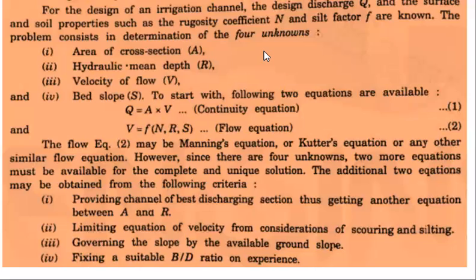And also the hydraulic mean depth R. So what is the hydraulic mean depth? I hope you remember about hydraulic mean depth, and this hydraulic mean depth is purely dependent on the ratio of the cross-sectional area of flow to the wetted perimeter of the channel.